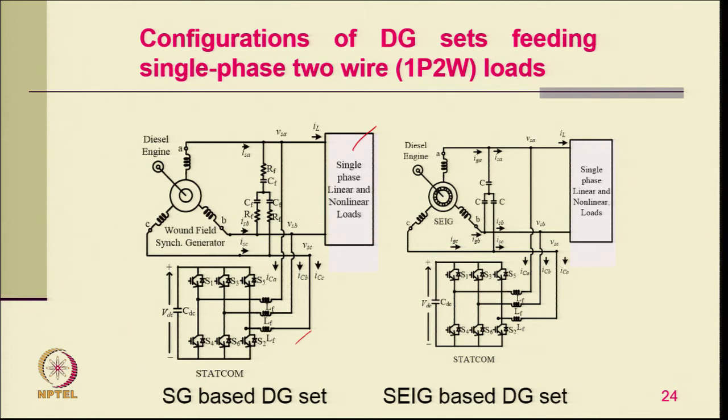Moreover, you can operate this generator in the optimum fuel zone, which we will talk about a little later. You can call this the compensator; it improves the voltage profile, provides load balancing, harmonic mitigation and reactive power compensation on the generator, so that generator losses are reduced.